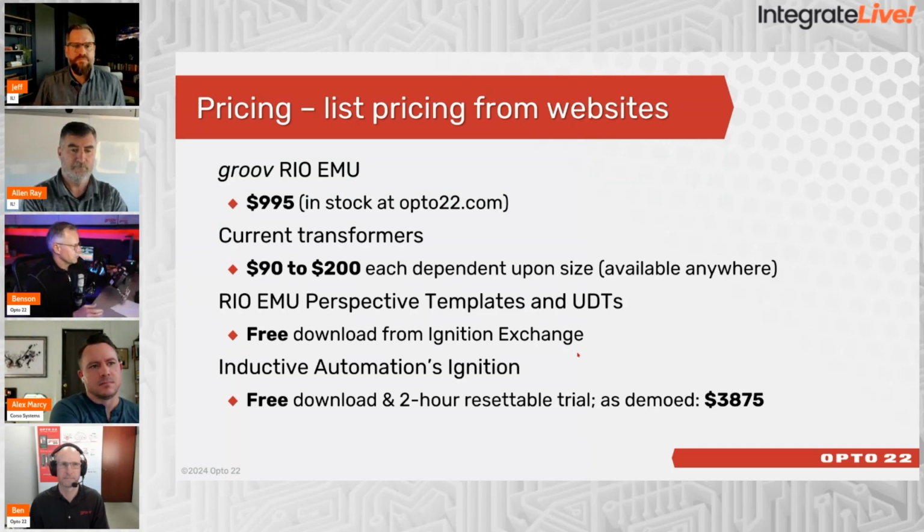A bigger one like this, a 600 amp CT, is roughly $130. So you just choose the CTs sized properly for the load you're trying to measure, and wire them up to the EMU. And of course, with the voltage tap, now you have current and volts, just as described.